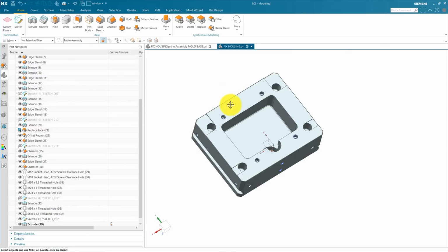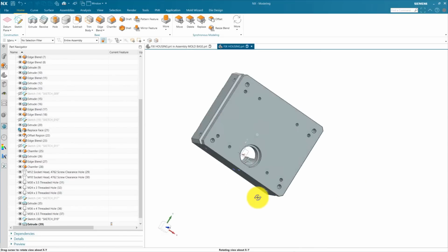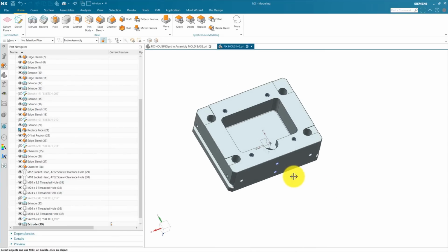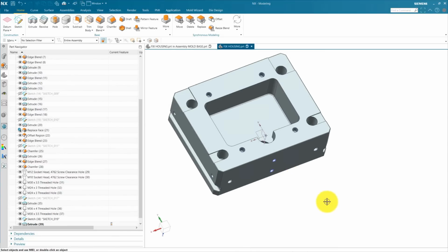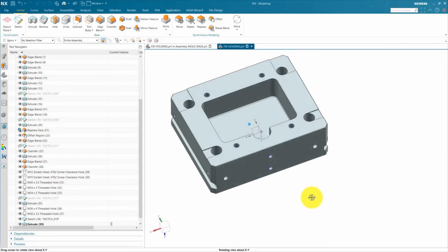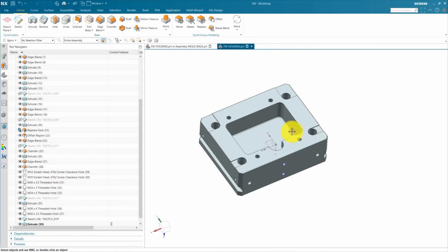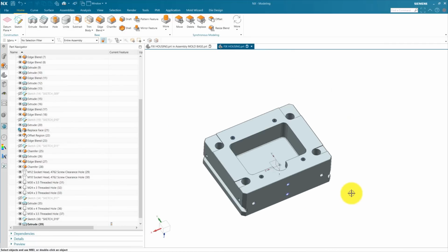And when there is any slide, we need to add the slide, and add somewhere a chill vent or some matching block. This is the ejector system we have to add. That is our basic fixed housing design. We can update this in a future video when required. In this video our fixed housing is complete.